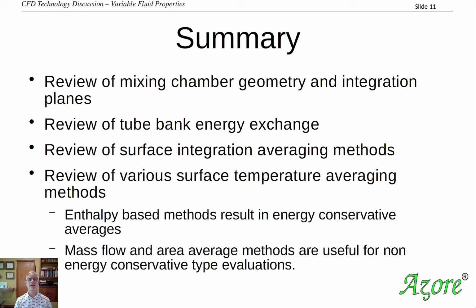We looked at how we set up our two tube banks. In this particular case, we were interested in removing a certain amount of energy, and we looked at ways of figuring out how to set our boundary conditions for that. Then we also looked at ways, in the second tube bank, of adding energy in to drive our fluid temperature to a specific temperature that we were told is what that system does.